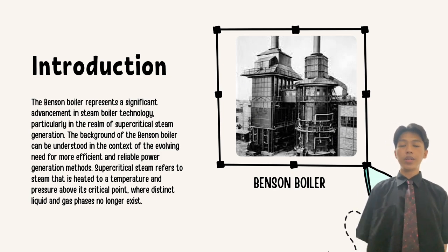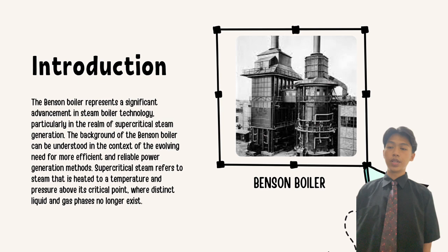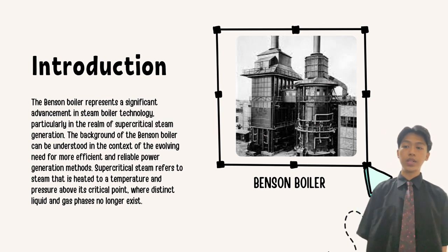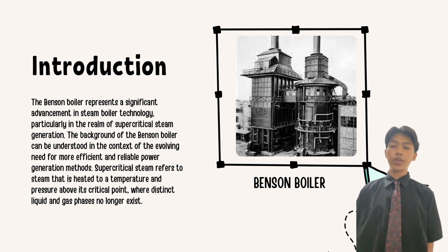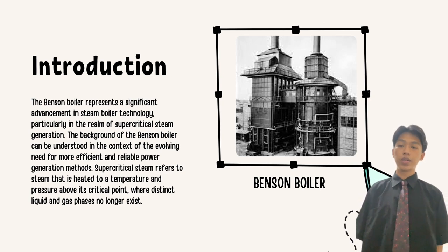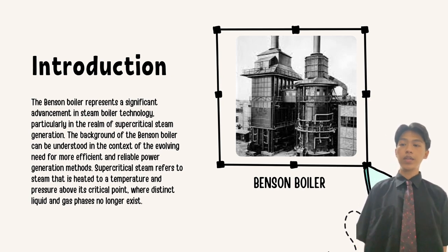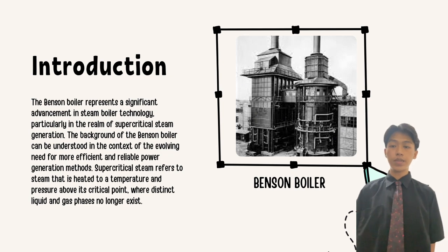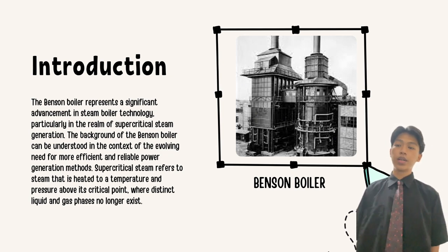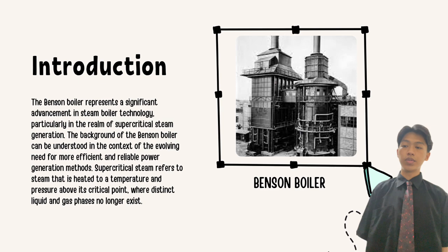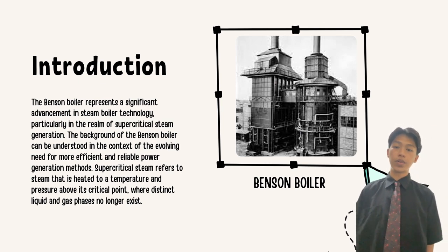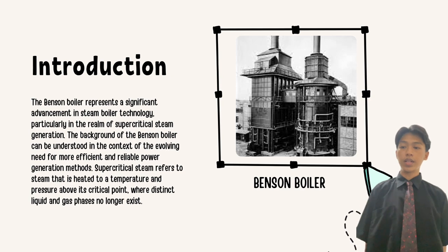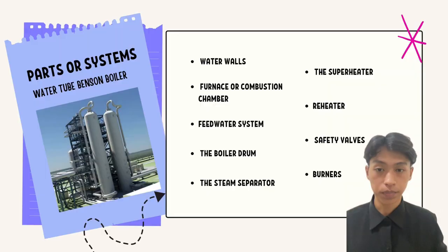The Benson boiler represents a significant advancement in steam boiler technology, particularly in the realm of supercritical steam generation. The background of the Benson boiler can be understood in the context of the evolving need for more efficient and reliable power generation methods. Supercritical steam refers to steam that is heated to a temperature and pressure above its critical point, where the distinct liquid and gas phases no longer exist.